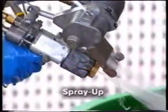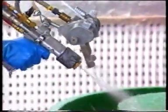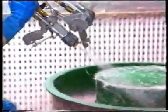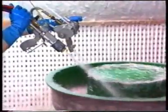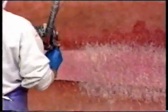With the spray-up method, resin is sprayed onto a prepared mold surface using a specialized spray-up gun. The gun simultaneously chops continuous reinforcement into suitable lengths as it sprays the resin. Fiber reinforcement is mainly chopped E-glass, and it may be accompanied by additional reinforcement such as woven roving.